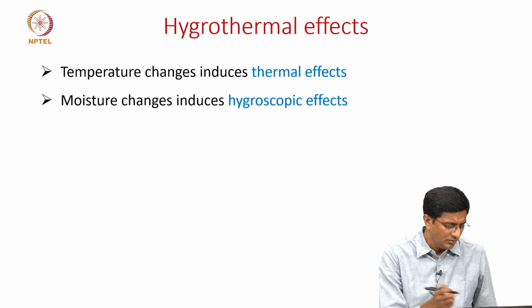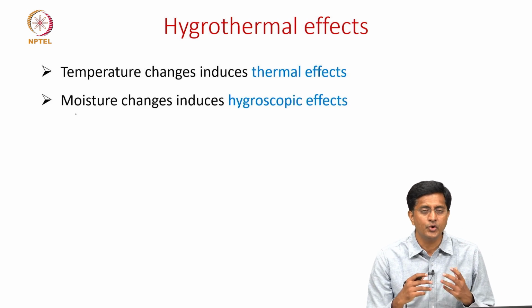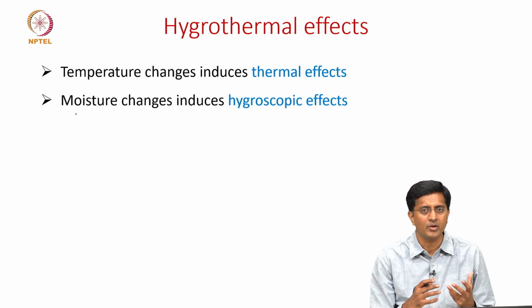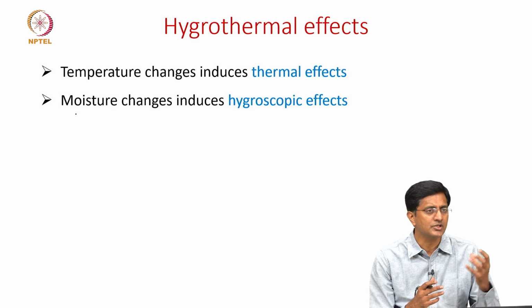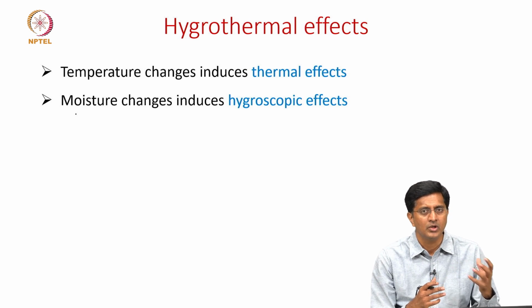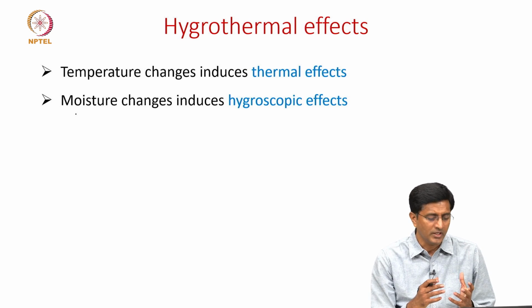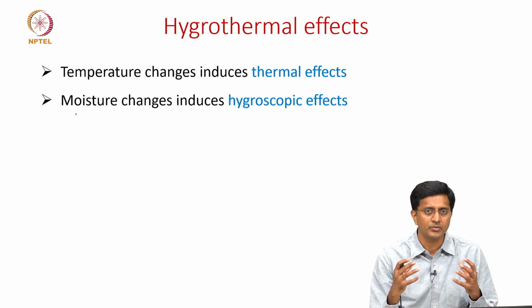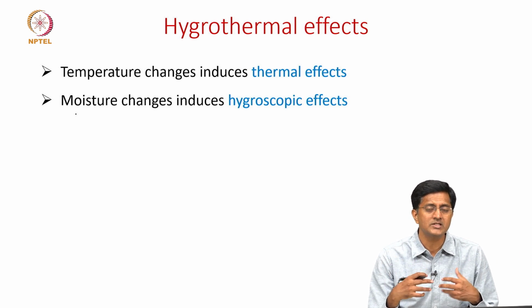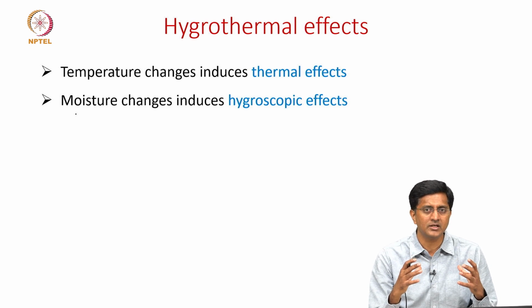Similarly, when it is exposed to humid environments, let's say we have a composite structure which is passing through a humid environment, then it absorbs the moisture from the environment and there is some swelling happening. Because of this swelling, there is an increase in the volume of the material.